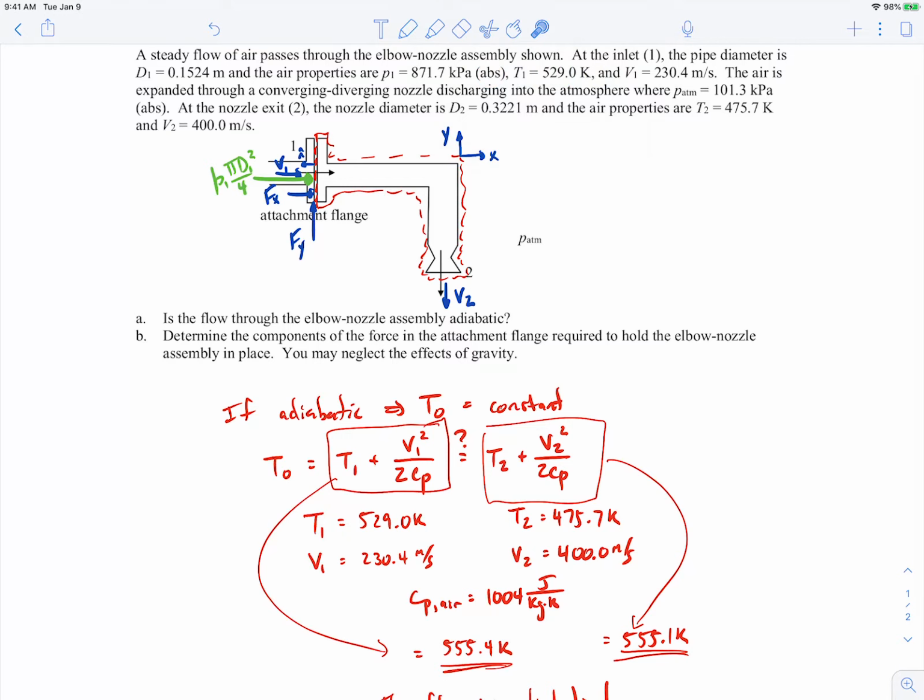And then what I'm going to do is I'm going to use a gauge pressure everywhere. So if I use a gauge pressure everywhere, then everything along the surface is 0, right? Because it's all exposed to the atmosphere. Down here, the pressure is potentially different from atmospheric. We don't know what it is yet. But that pressure force would act in the vertical direction, so it doesn't even factor into it. So I'm just going to go ahead and use the gauge pressure for this, and that'll be our only surface force besides the Fx. So let's go ahead and write that down.